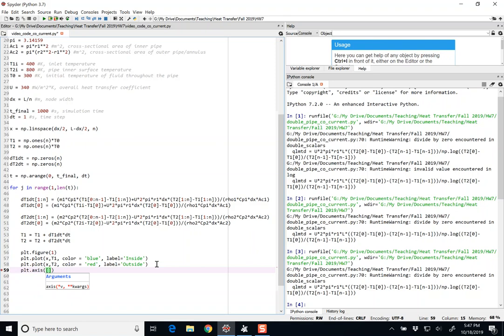We're going to want our x-axis to go from 0 to L, and we're going to want our y-axis to go from 298. So we're just catching our... we know our initial temperature is 300, and then after that we're going to have an 800-degree fluid exchanging energy with a 400-degree fluid. So we should have an upper limit of 820, which, thermodynamically, nothing can go above 800 in this system, so that should catch everything.